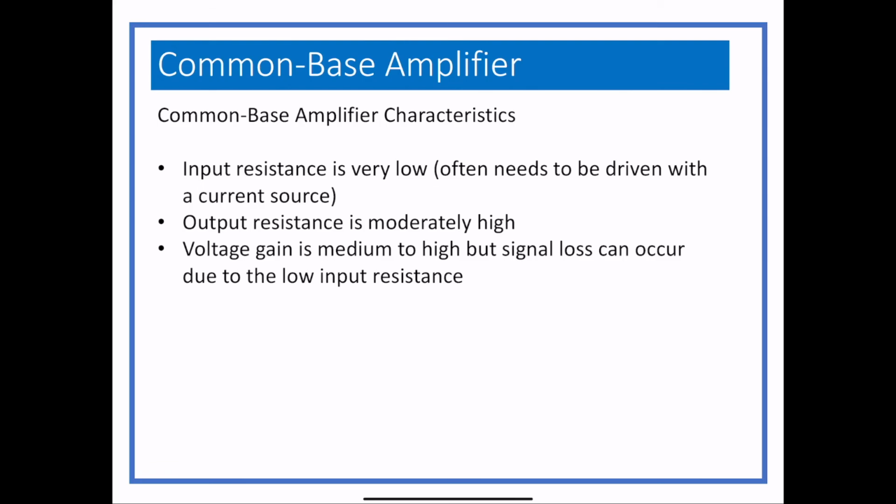It does work really well at high frequencies. That's probably its saving grace and why it exists at all, because there is a type of interaction with feedback capacitance with common emitters, which we don't cover in here because we don't cover frequency response. There is feedback capacitance that occurs with common emitters that does not occur with the common base. So if you're using high frequencies, it actually works really well.